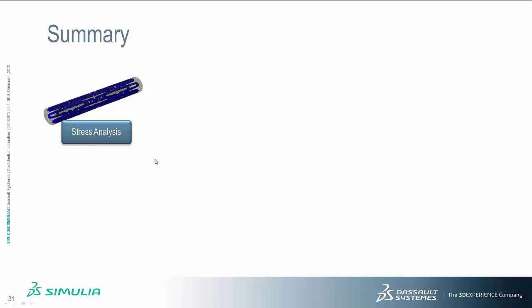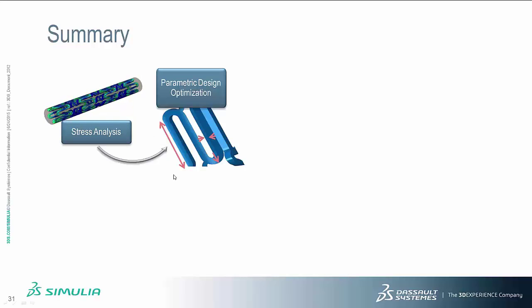To summarize, we started by showing you how to conduct the stress analysis for the crimping and the deployment of the stent. We talked about how parametric design optimization can be used to improve the stent and reduce the stresses in it. Parametric design optimization is used to change geometric parameters that can be easily changed once you have the initial shape of the stent, such as length, radius, and width or thickness.